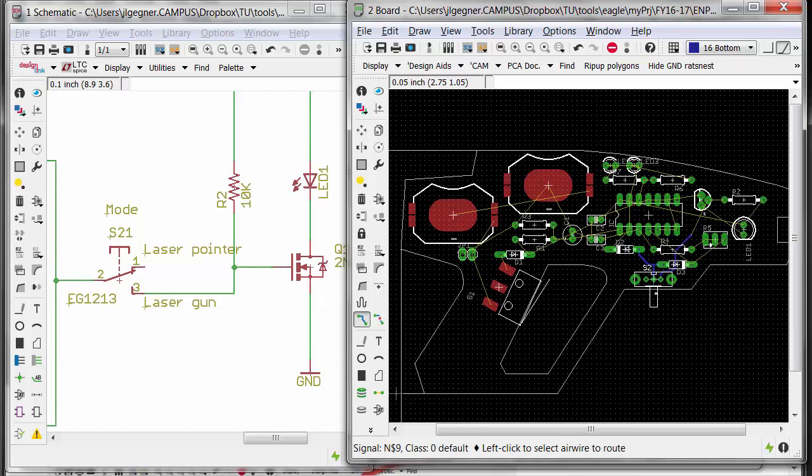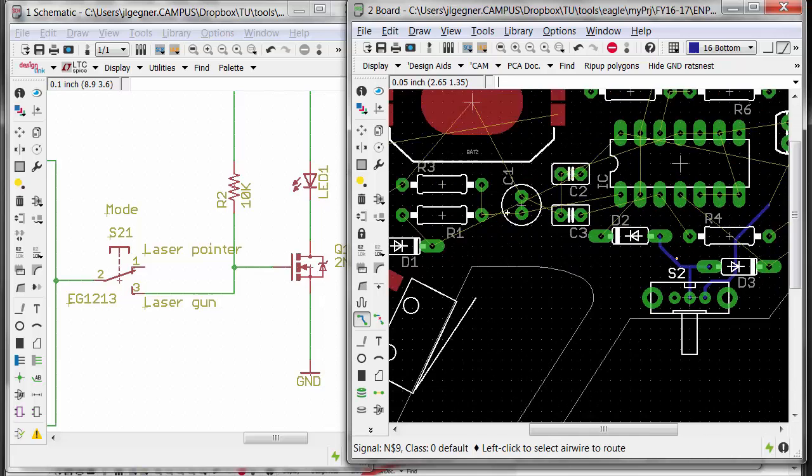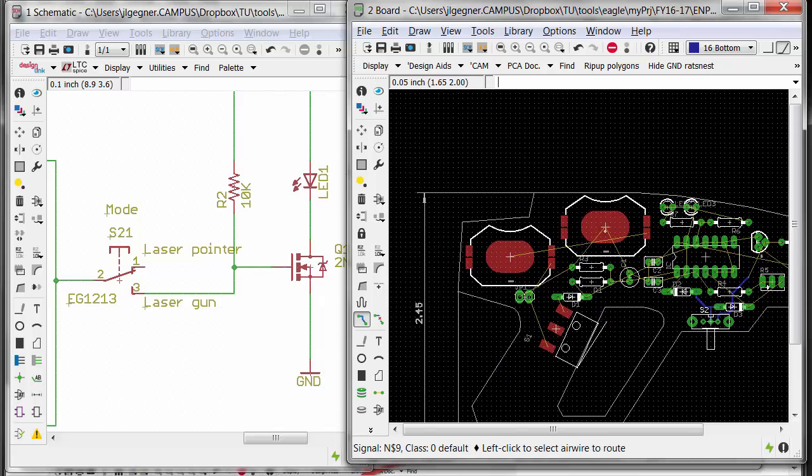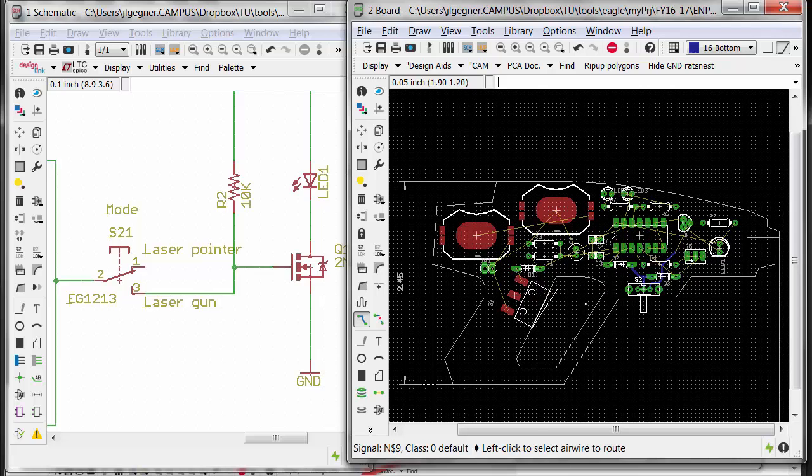So the rule is that to make the soldering easiest, if you place the parts all on the top, then you want to make all the connections on the bottom because that's where you're going to be soldering. So you should try to route your board completely using blue traces in this case because the parts are on the top. Now I have an exception here: in my final design, one of these battery holders is actually down on the bottom. But we treat surface mount parts a little bit differently. Here you only have 2 of them to contend with, so it doesn't matter. If you choose to use surface mount battery holders, you can put them on either side, or one on the top and one on the bottom.